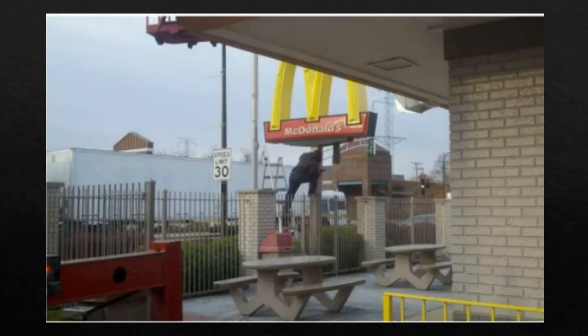Remember to always position a ladder in such a way that whatever work you're doing, you don't have to overreach on the ladder. Remember, think about the belt buckle. The belt buckle should never go beyond the vertical members of the ladder. You see, obviously, in this case, this person who's painting the sign post is greatly exceeding their reach on their ladder, and in fact, they're using that fence for support.